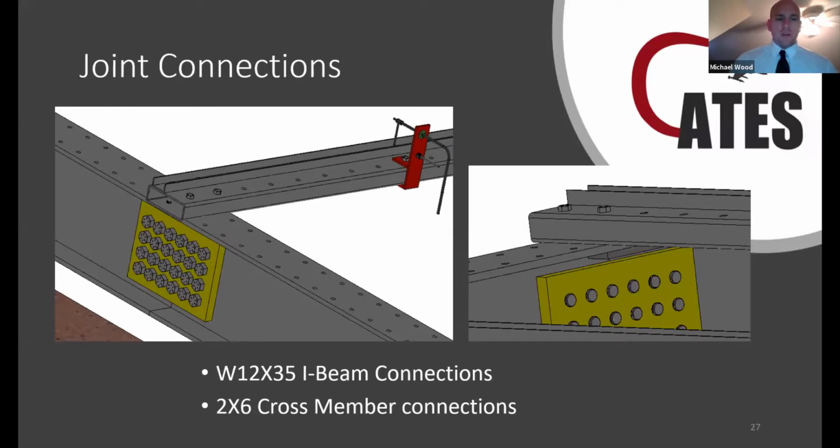So in order to configure our design to different test cells and our spacing, we had holes drilled every 3 inches along our cross members and every 4 inches along our I-beams. So our design had to have strong end-to-end I-beam connections that would handle the stresses produced during the operation of the test cell and during lifting of the structure onto the exhaust stack from the ground.